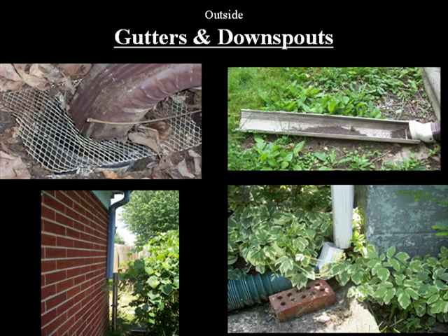The picture on the top right is a rain diverter pan, however, it's angled upward, so all the water is still accumulating around the foundation of the house. And the picture on the bottom right is a simple fix. However, right now, the only thing that's happening is water is accumulating around the foundation.